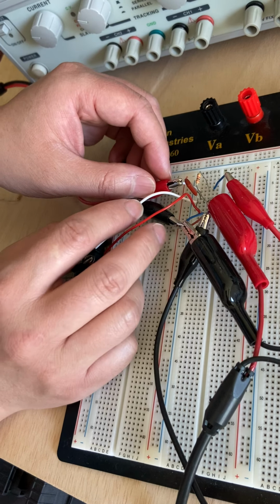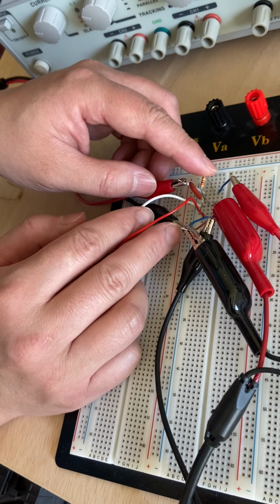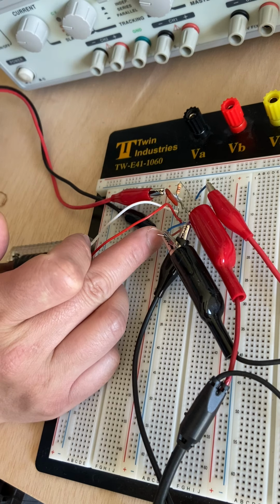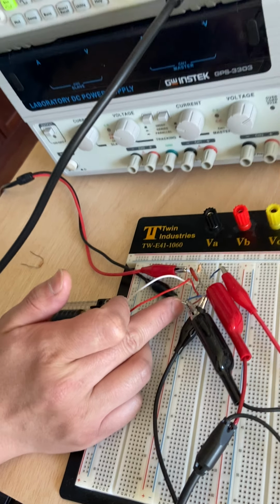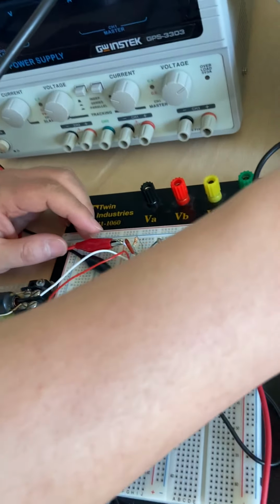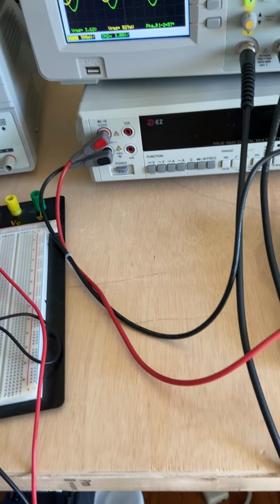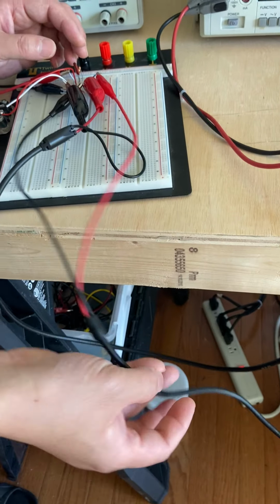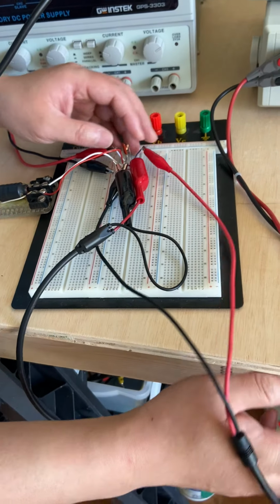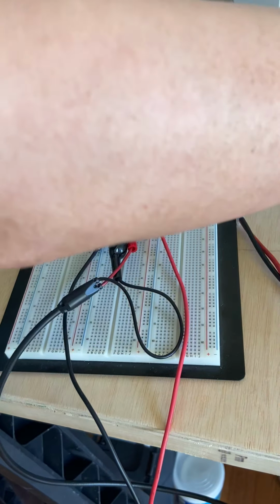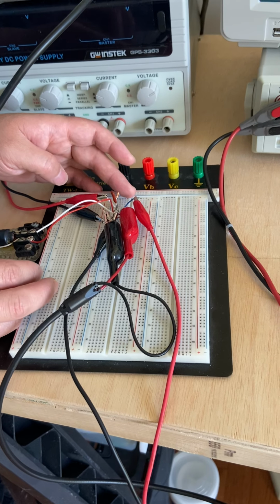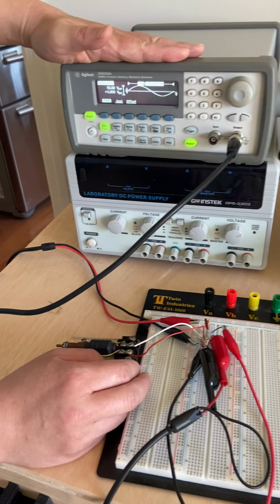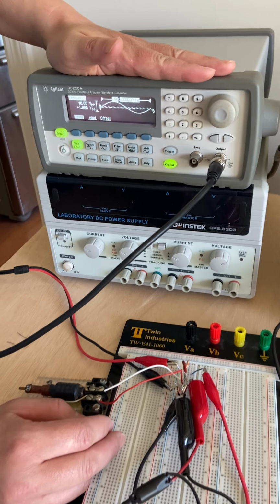We are connecting the input across one end of the resistor and the ground, connecting to one end of the capacitor and one end of the inductor, to the function generator. The first channel of the oscilloscope is connected to the output of the circuit, which is across the capacitor and the inductor. The second channel of the oscilloscope is connected to the input, which is monitoring the signal from the input of the circuit, which is the output of the function generator.